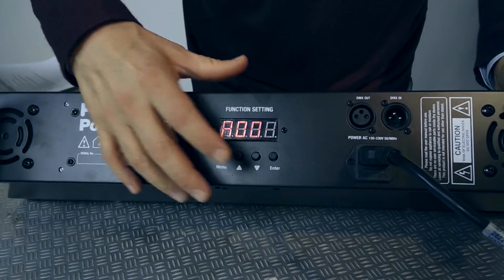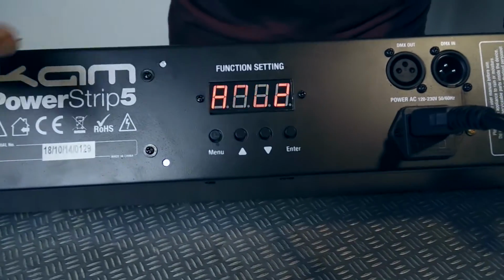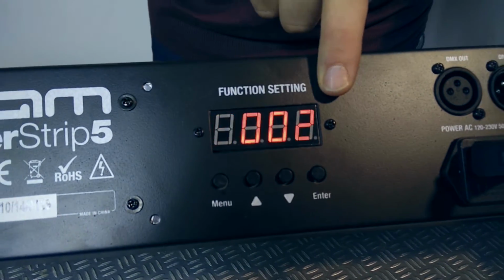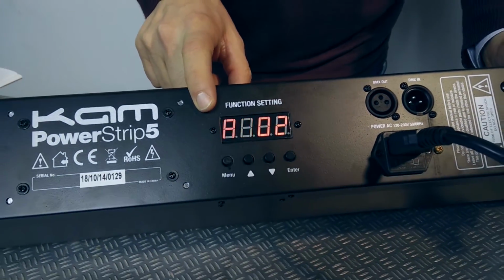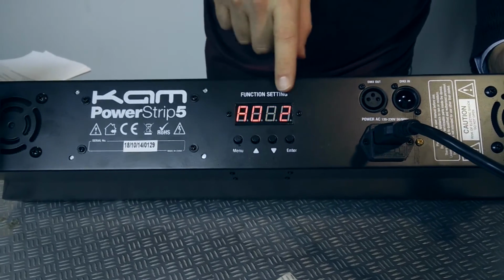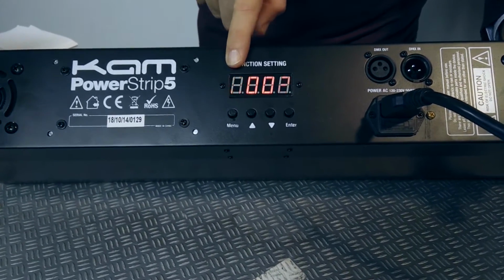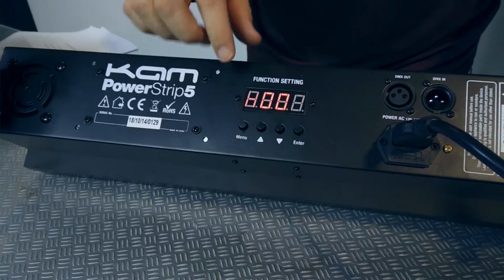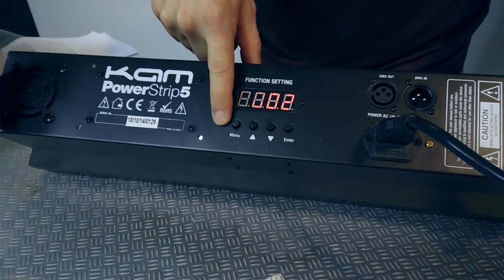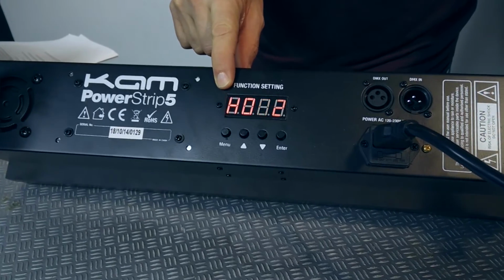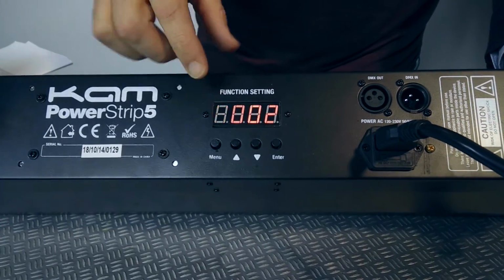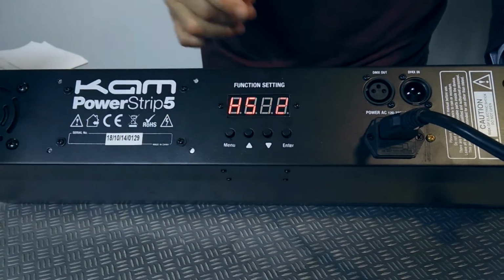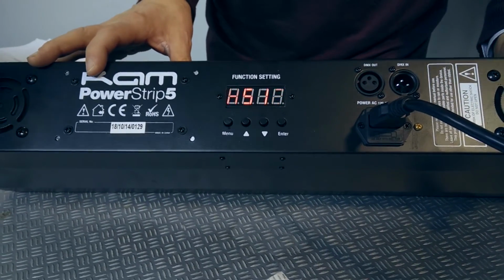This particular unit is broken down into 3 DMX sections. If you see A, and obviously the numbers after, that's for 8 channel mode. And what you do here, I was going to set that address there to 8 channel mode DMX value 2. If we scan through, pressing the main menu again, you come down to a capital H, which is the 20 channel operation. And obviously you can set the DMX value between 1 and 5, 1, 2 for your universe.